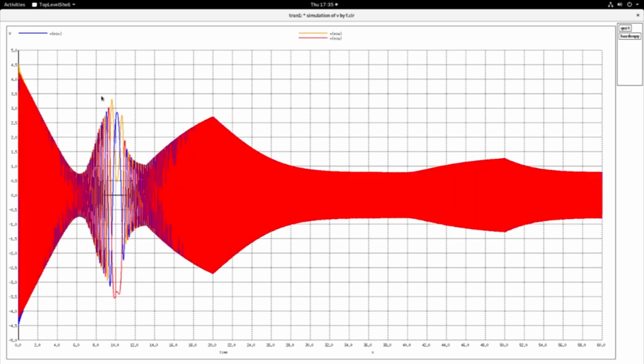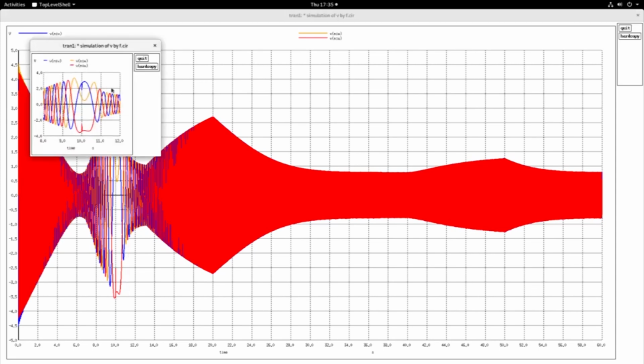This portion here is where you will see the shaft speed transiting from minus to plus, and you will see that the three-phase waveforms will change sequence, rotating from clockwise to anti-clockwise in this zone, after it has crossed and become positive.